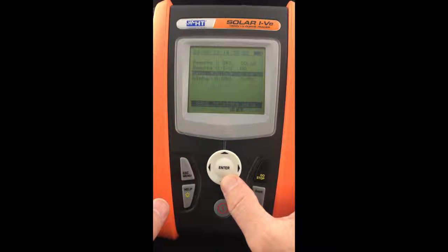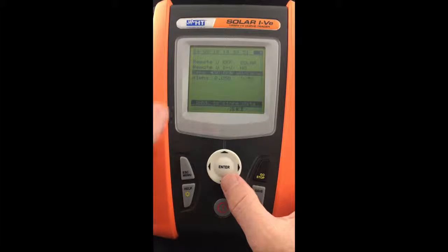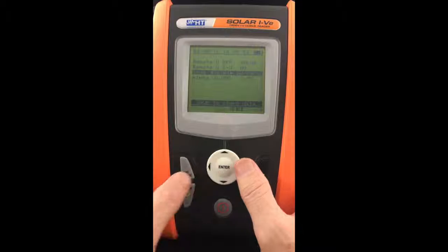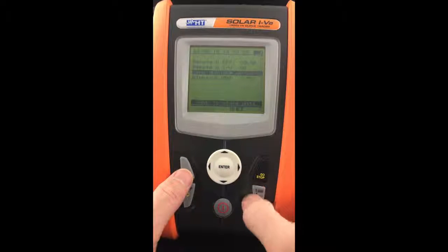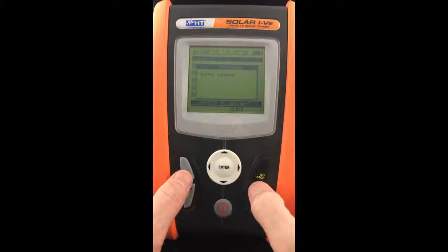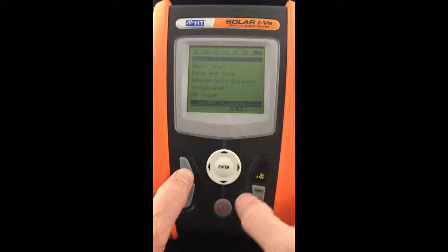Factory setting is 30. This has to be the same factor that's on the back of your 304N, which is the irradiance sensor. If it's set to 30 and the real number is like 24 or something, the irradiance measurements are going to be off by 20 or 30%, and that's a big problem. So set this to wherever it is on the back of your 304N, save it, and then we'll go back to other things. Thanks.